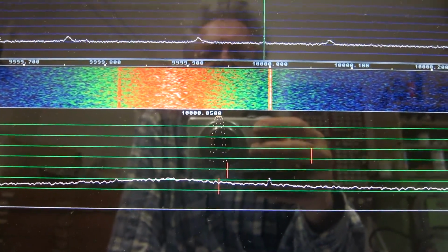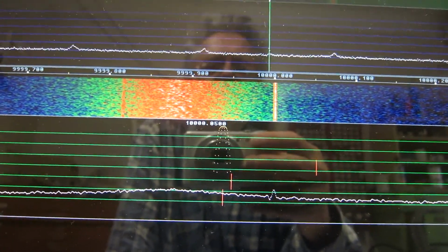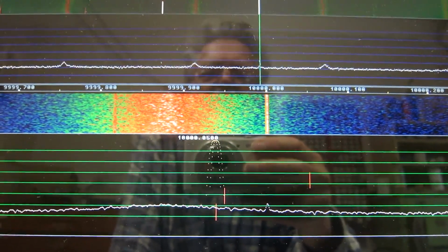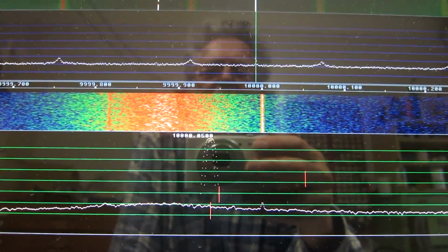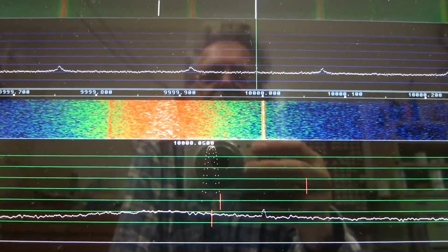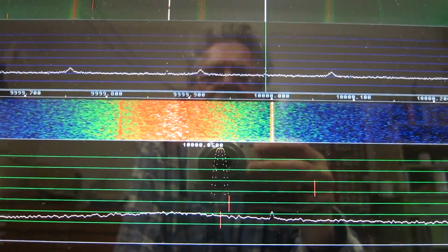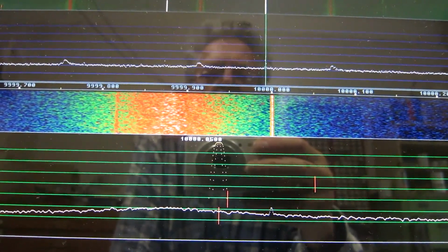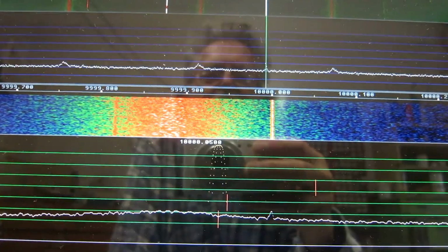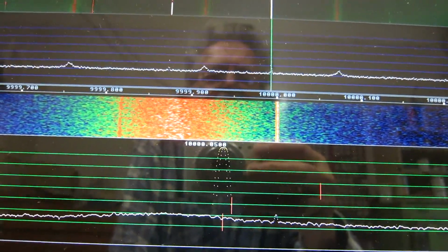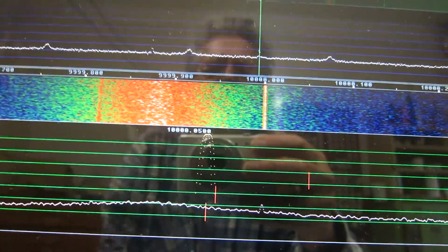And it seems to me to get a better sideband noise level, I need to improve this signal-to-noise ratio because I cannot improve the Q. That would be far more efficient, but not possible without another type of crystals that would cost about 100 times more for each one. On the other hand, I wouldn't need as many, but on the third hand, then I couldn't get as good performance at wide separations as I can with this arrangement.